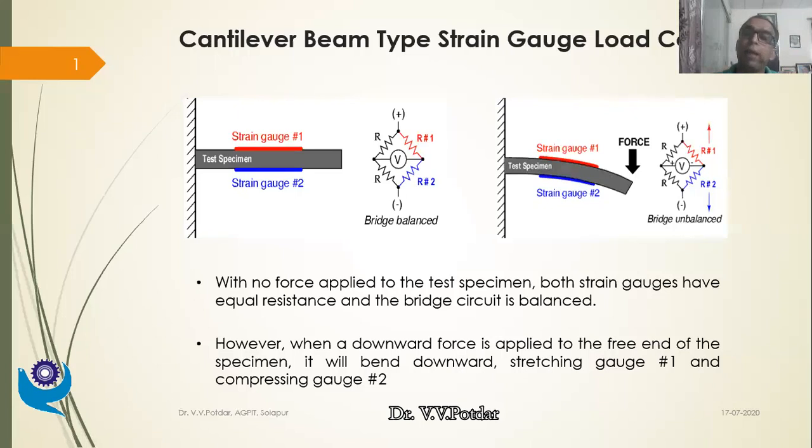Okay, so if you look at the load, F is acting at this beam length of L, isn't it? F is acting at this beam length L. So this F is acting at this L. Let us try to find out the theoretical strain first of all. We have studied these things in strength of materials, just to recollect. So how much will be the bending moment on this cantilever beam? This F into L will be the bending moment.